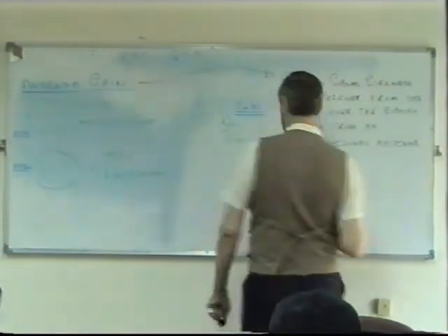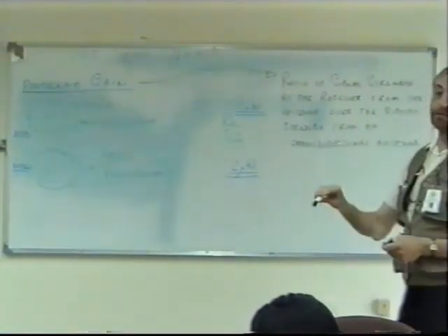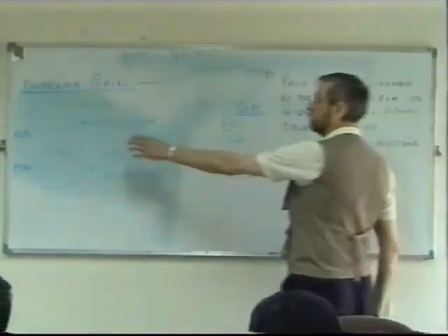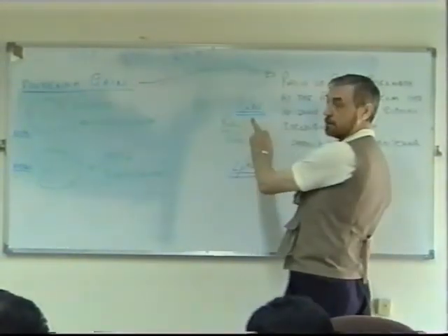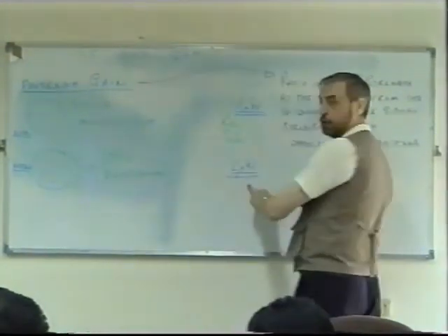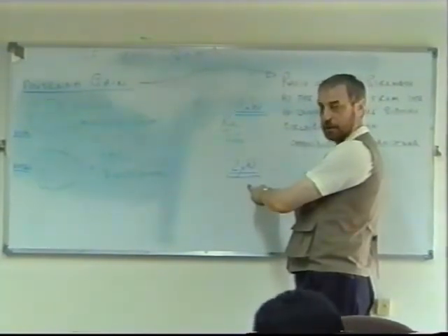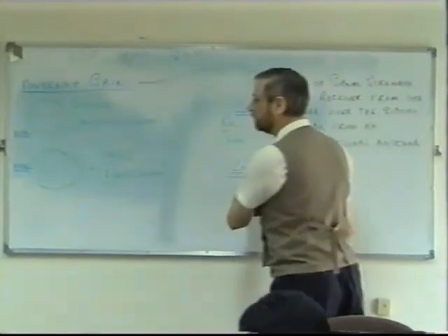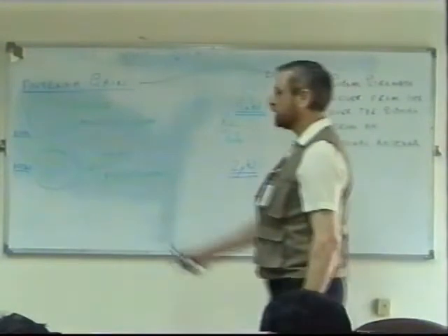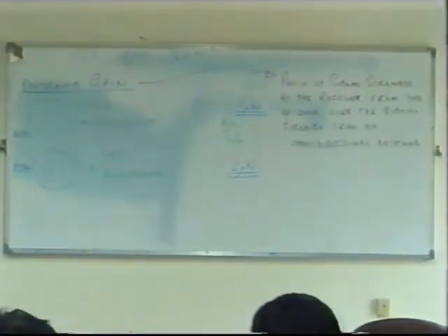So it's a ratio of the signal strength you receive for your particular antenna compared to what you would receive if it was an omnidirectional antenna. So in this example, I would receive 1 microwatt if it was omnidirectional, but for the same power here, 2 microwatts. So I get twice the power because I'm using a different type of antenna. I haven't changed the power of the transmitter, I've just changed the type of antenna I'm using.